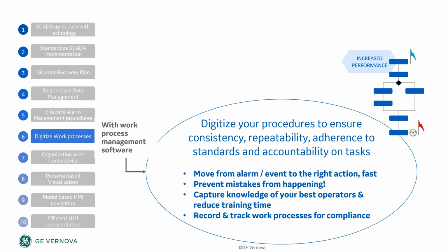What we are seeing increasingly, and what we have seen be very effective, is getting these work processes integrated into your SCADA systems. How can some of the information that you're getting from the field, whether it's an exception, an alarm, or a data change, trigger a work process that is needed, and how can you consistently have an operator react to the alarm over and over again?